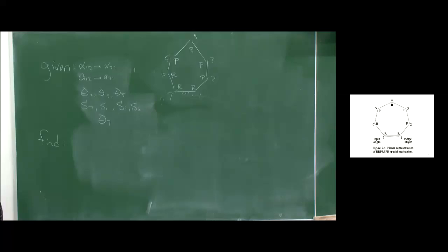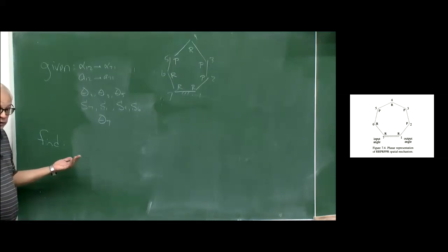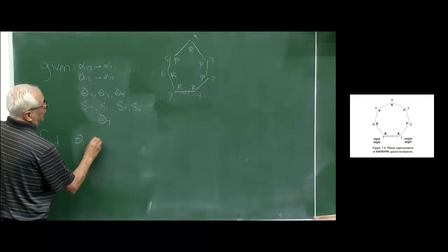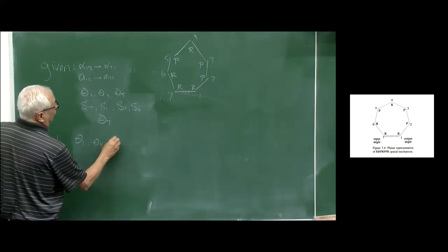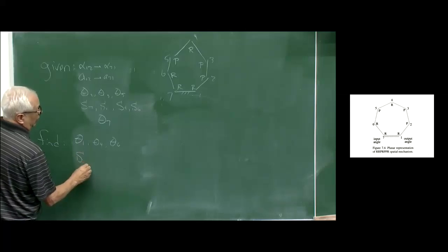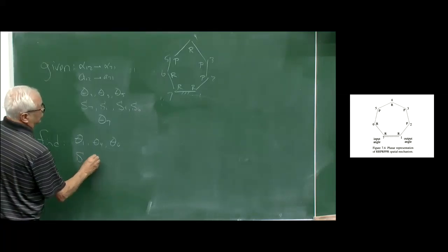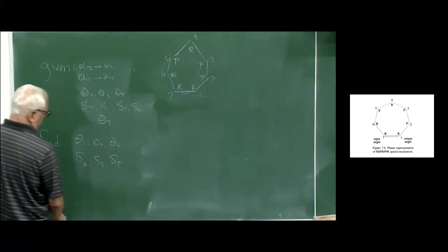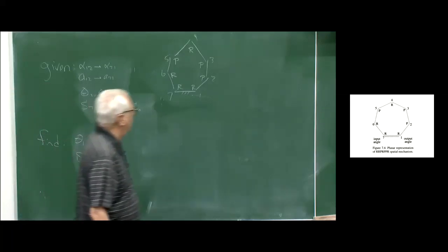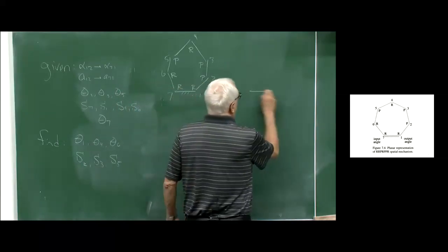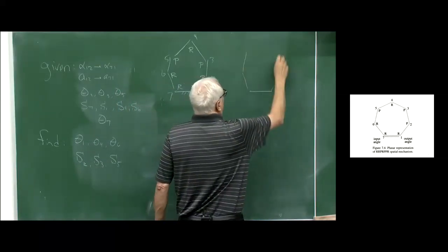What are we looking for? It turns out there's always in these group 1s, going to be 3 angles and 3 distances. So the angles are theta 1, theta 4, theta 6. And then where the prismatics are, we need to get these offsets, S2, S3, and S5. So there's our problem statement. We're going to draw the planar representation of the equivalent spherical mechanism.